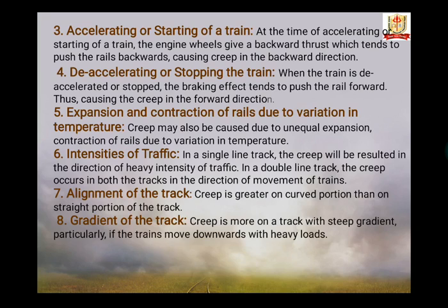Next is alignment of track. Creep is greater on the curved portion than on the straight portion of the track. Gradient of the track. Creep is more on a track with a steep gradient, particularly if the trains move downward with heavy loads.